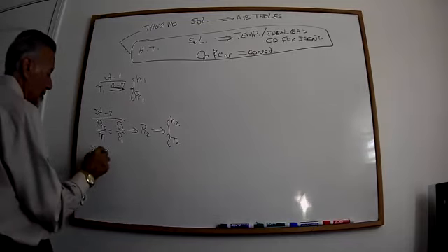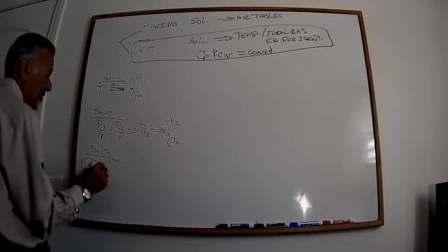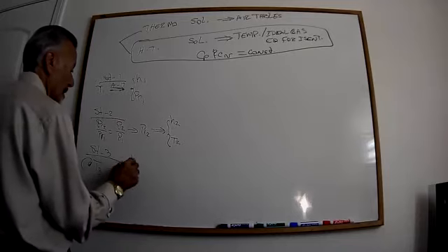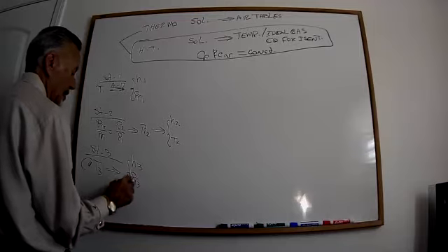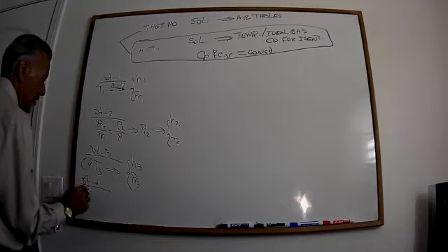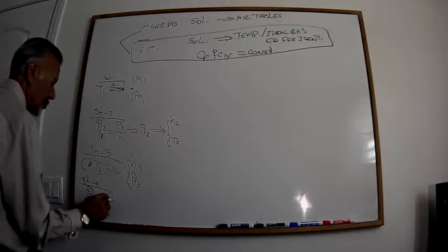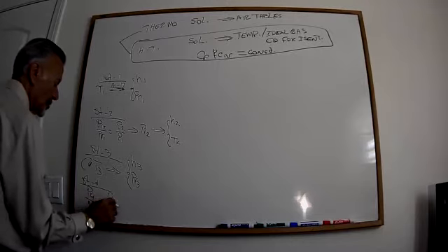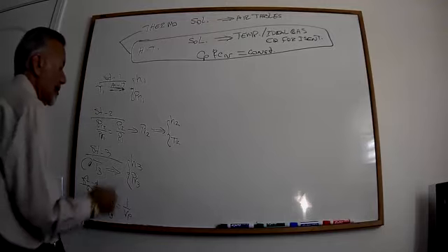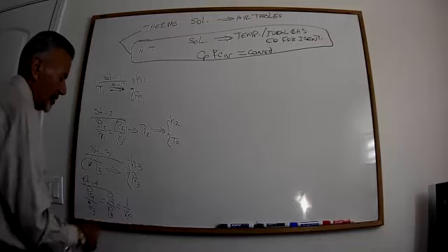At state 3, again, at the value of T3 that is given, you go to the table and find H3 and PR3. At state 4, once again, PR4 over PR3 will be equal to P4 over P3, which is 1 over R of P. P2 over P1 is R of P. P4 over P3 is the reverse of that.